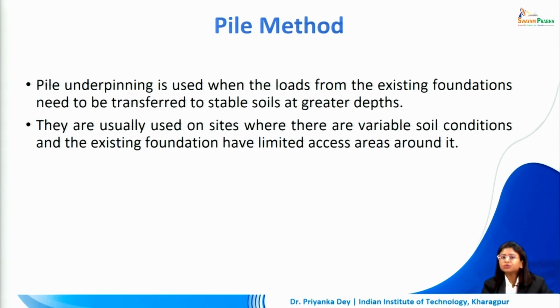Now there are usually some sites in which there are variable soil conditions and there is very limited access to the foundation because of the shortage of area or space around the building. So in that case also we can opt for the pile method.